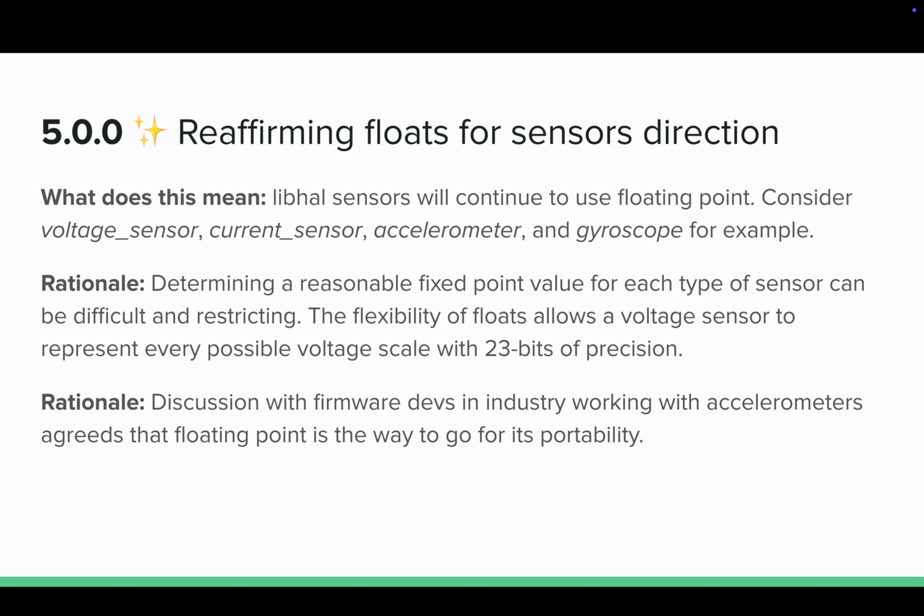One of the things that they expressed to me is that it really depends on the accelerometer and what it does for you. For example, some accelerometers will give you back the information in a really simple and easy to acquire way. Some of them will have temperature compensation. So you read out the accelerometer values, and then at the same time read out a temperature sense value right after the accelerometer or IMU data. Then the vendor may give you some equations to use in order to couple the temperature sense data into the accelerometer data and gyroscope data, compensate for it, and then use those numbers to actually come up with what the G's would be based on what you set the maximum scale to be.